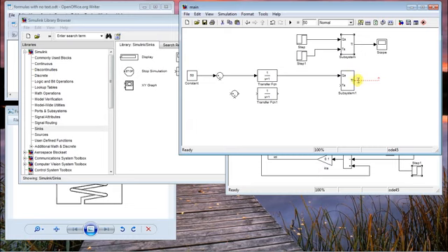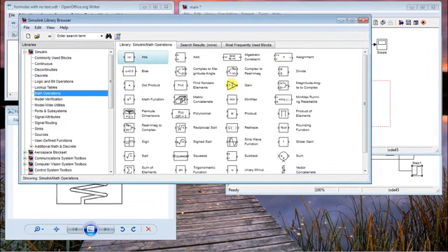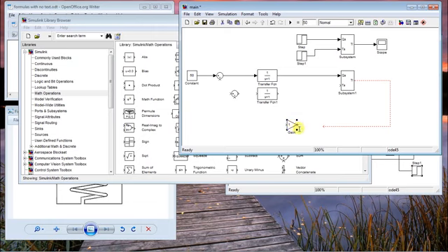Now I'm going to use the same system here again. That's why I'm going to delete this old one, place the system with the perturbation here as well, and let's see how this system now behaves. As a measurement element, I'm going to use a gain block of 1, which doesn't change anything, but we have a measurement element.